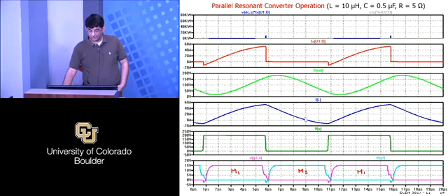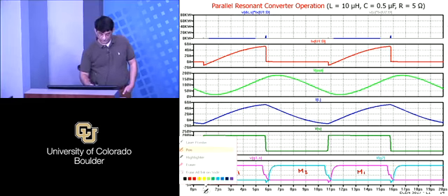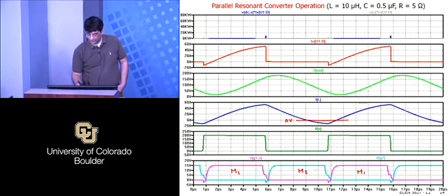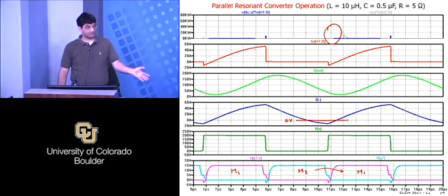And again, the key thing here is that I have negative current in the inductor at that transition, right? The transition from M2 to M1, which was the transition that troubled us, again has negative current, and so again that power loss is gone, right? Same phenomena, same everything, except waveforms are slightly different, but the fundamental thing here was that the current was negative.